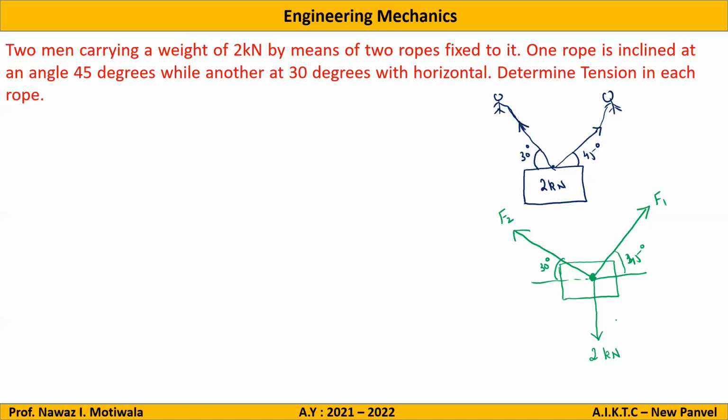Now what can you comment? By looking at the free body diagram, what can you comment? Concurrent forces. Three forces are acting in the same plane. We can apply Lami's theorem. Correct. Because you can see only 3 forces acting at the same point, I can tell that it is a problem of Lami's theorem. You can solve the problem by Lami's theorem basically.